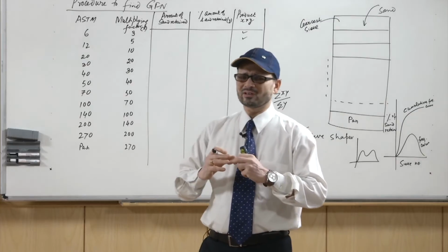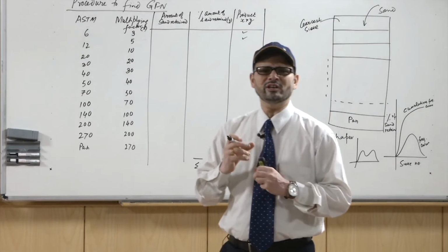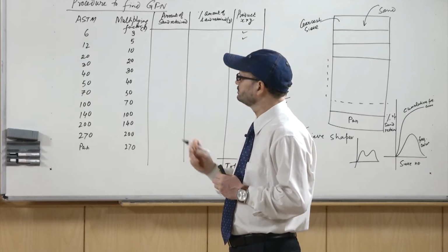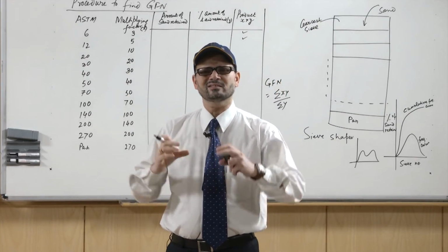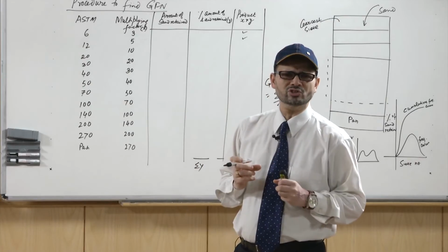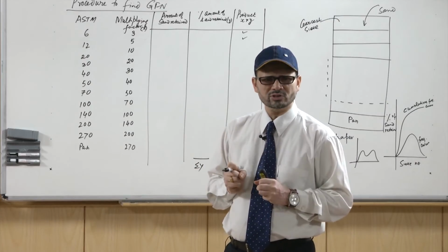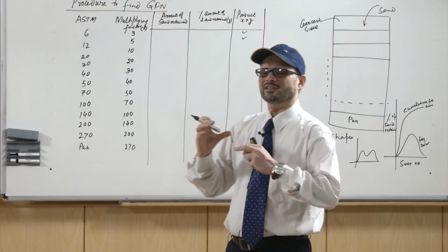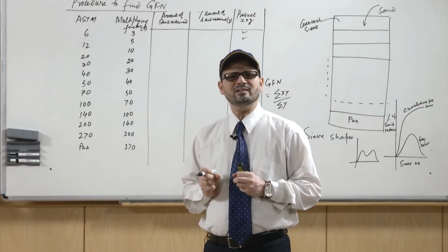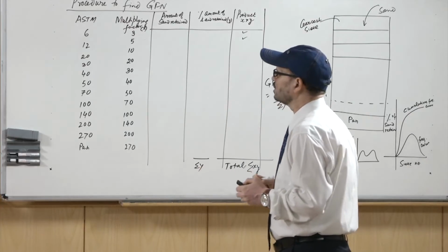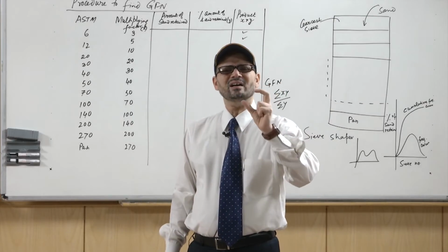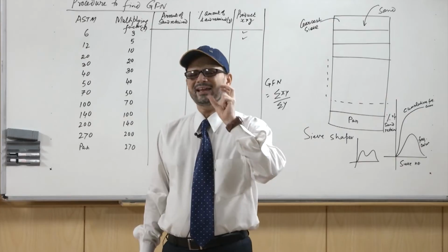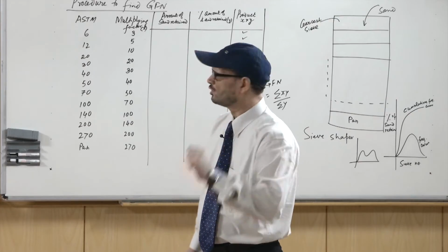If you have more than the required amount of moisture, it may lead to a lot of defects, like the formation of blowholes or pinholes, because these will be trapped inside the casting. So, there are tests which can tell what the amount of moisture in a particular sand mold is.